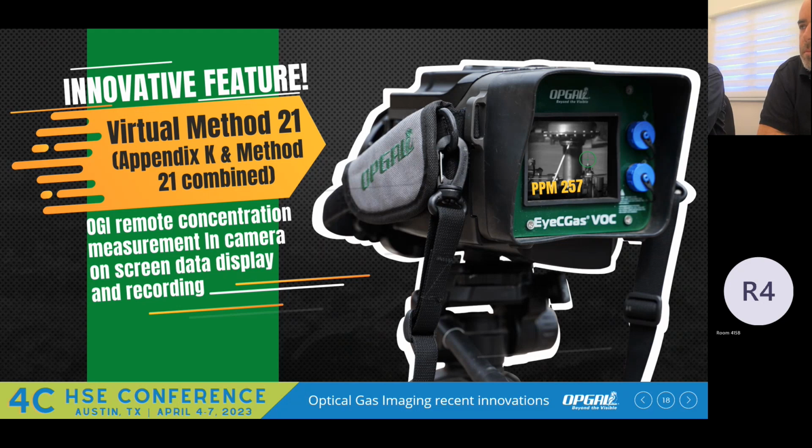We will have all the quantification in fluxes, in grams per hour or cubic feet per hour or per minute. We will have all the units of quantification in the camera. So we're starting with evaluating the concentration and the maximum concentration in the plume during the measurement, and the measurement will be recorded on the image. As you can see here, it will give the reading on the screen, and it can be recorded with the video, what the concentration of the leak detection event was.